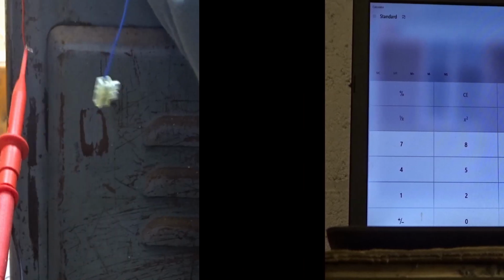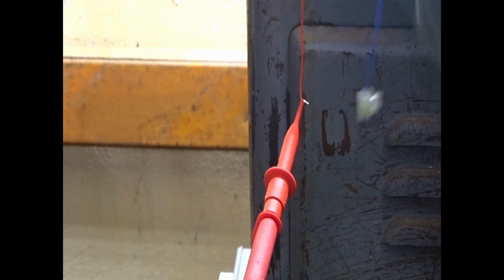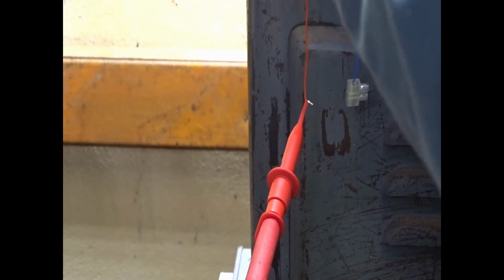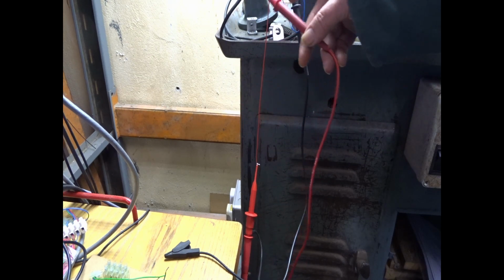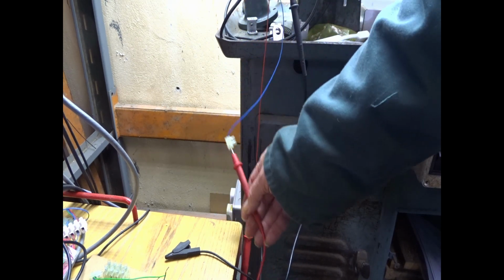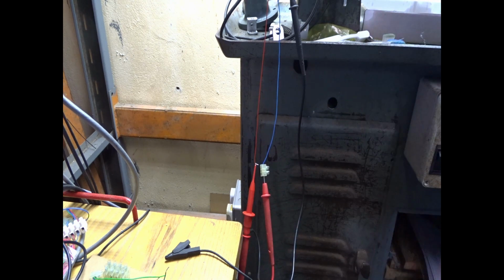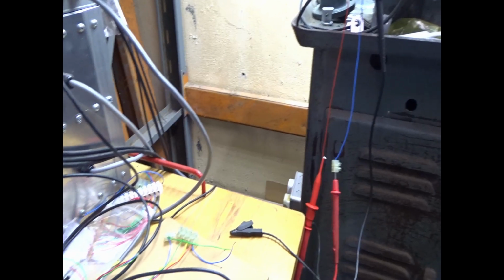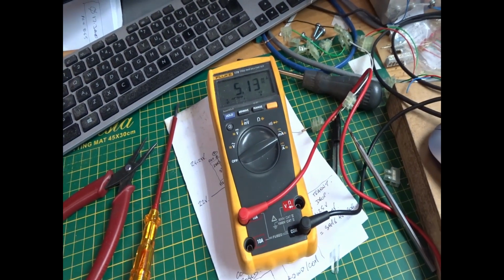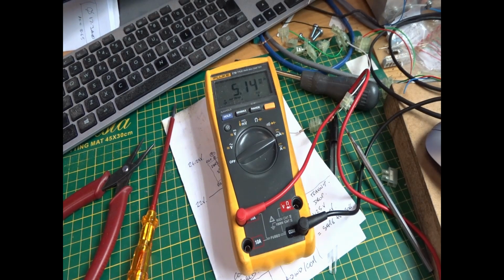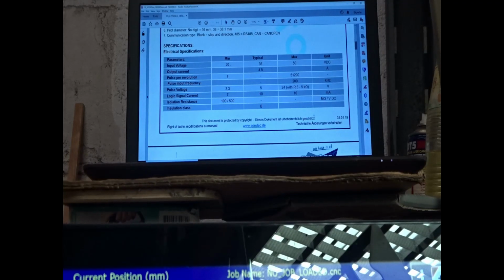Now 5 milliamps seems a little on the low side. Can I check it? Is it normally low? Okay, and there's the two leads connected on the way back to the series resistor after the pull minus, and it's connected to an ammeter, and I'm getting 5.13 milliamps, which is out of spec. It's too low. I need to raise it.